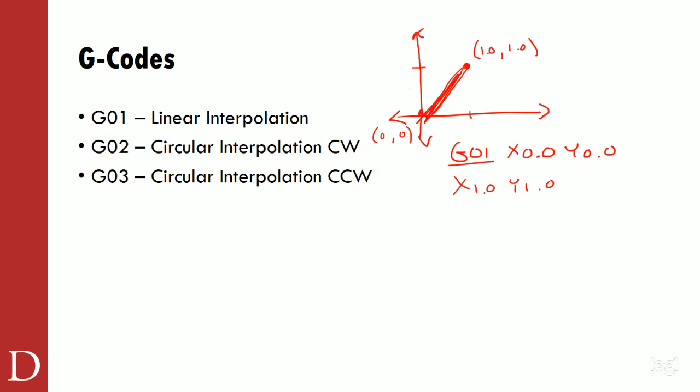When we talk about a G02 interpolation, what we're really talking about is the ability to create a circular arc. And as soon as you see CW, we're talking clockwise, and CCW means counterclockwise. As an example, if I drew up again a nice little coordinate system, here's my X and my Y axis. There's X and there's Y. And let's say I go out 3 places now, 1, 2, and 3.